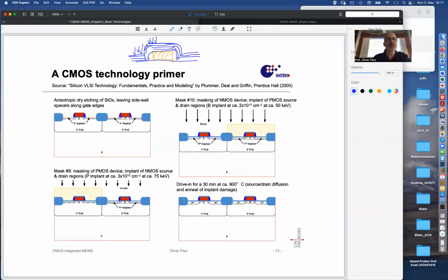So this is still there because the thickness to etch vertically is twice as thick, or different from the thickness here. Here we only have this thickness, here we have this large thickness. So when we remove vertically a given thickness, we are left with some structure. And this is called a sidewall spacer. That was structured without photolithography, just by intrinsic technological know-how. Very handy.